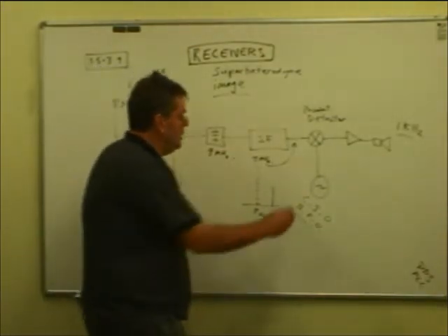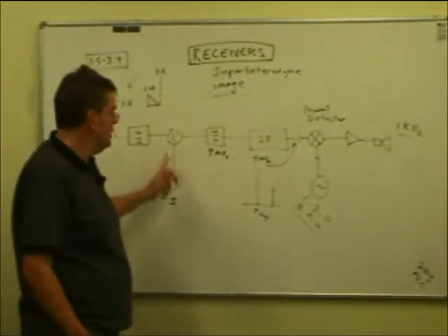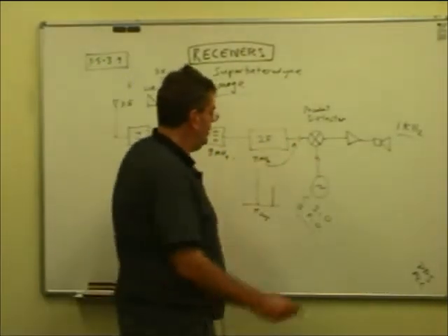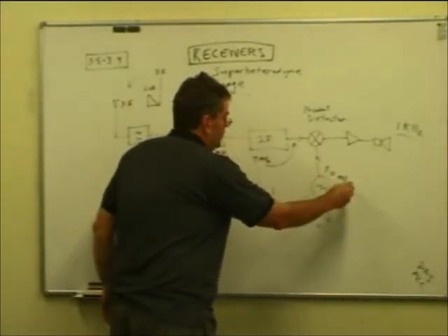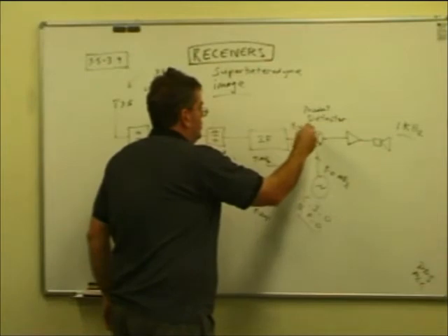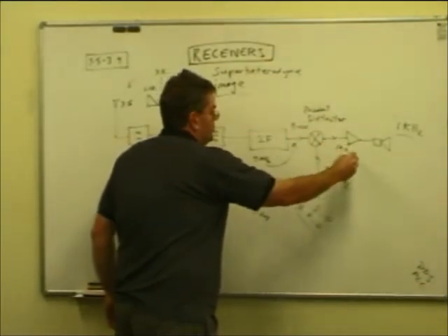We feed 2 signals into it, just like we did here, except we inject a carrier, so 9 megahertz, and you've got 9.001, so out comes 1 kilohertz, our original sound signal,